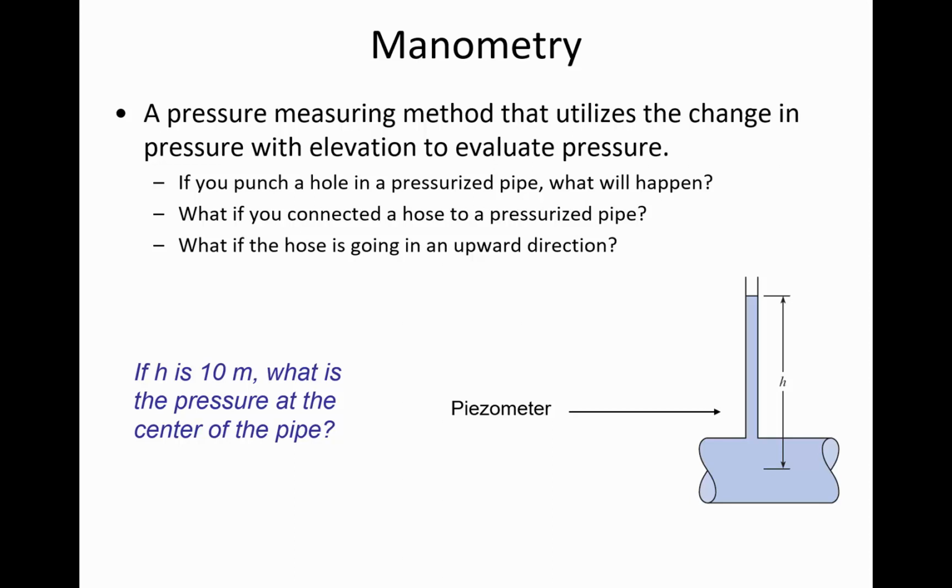So think about if you were going to try and measure the pressure of water in a municipal network with piezometers like this, rather than using pressure transducers or some other method. If you only had access to a piezometer, then the range of pressure inside of a municipal network is between 240 kilopascals up to as high as 850 kilopascals.